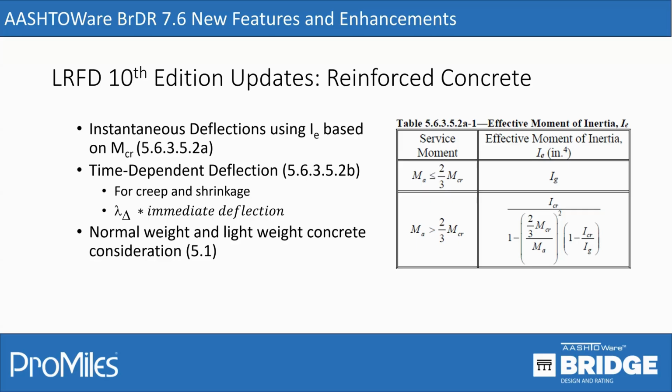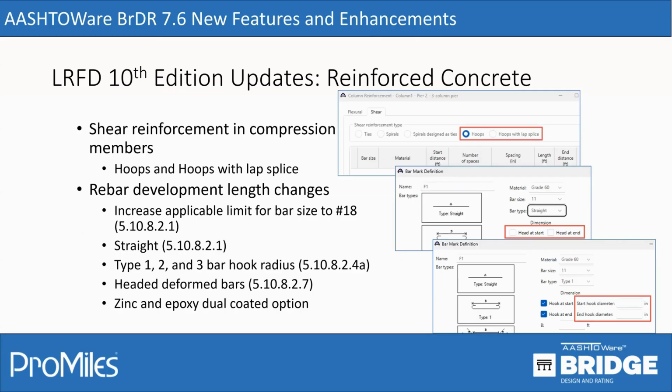And it's based on the service moment. There's also an implementation for considering time-dependent deflection for creep and shrinkage for reinforced concrete. It's essentially based on a lambda delta factor times the immediate deflection, being the deflection due to sustained loads for reinforced concrete section. Also, there were some updates for normal weight and lightweight concrete from section 5.1. Let's move on to the next update for reinforced concrete.